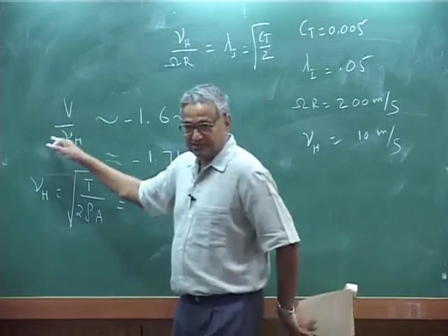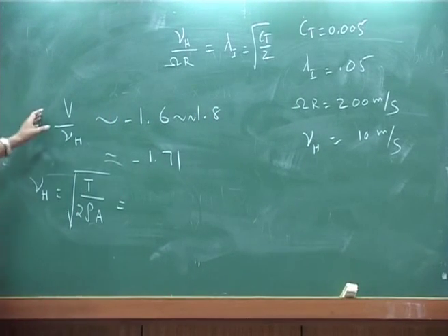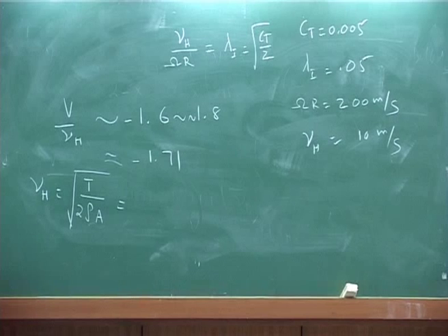If I multiply, okay, v is the descent velocity. Okay, so, it is a negative number. You will find it will be coming with about 17 meter per second. So, in the range of 15 to 20, 25 meter per second it will come down. It is not that it will come very slowly like a leaf. 15 meter per second is quite substantial, okay, in auto rotation.